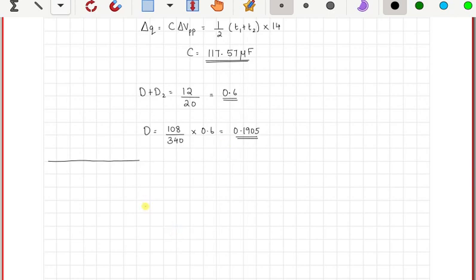So what has gone wrong here is that in all our calculations or in our designs, we considered all the components to be ideal, right? But that is usually never the case. If you take a source voltage Vg, it is always going to have an internal resistance, which may be small, rg, and any source that you take will always have this resistance. You can't do much about this. But this deviation from ideal characteristics we have not considered in our designs.